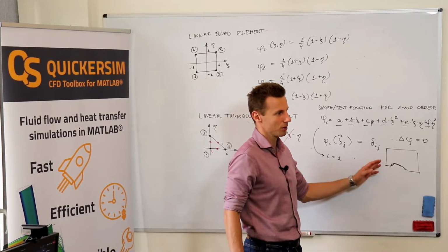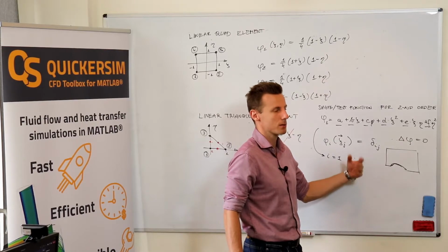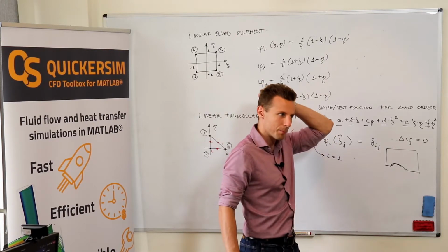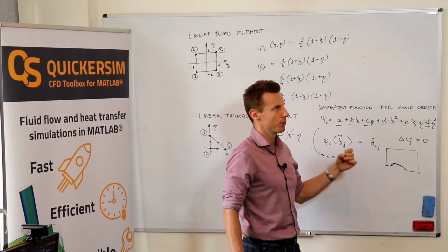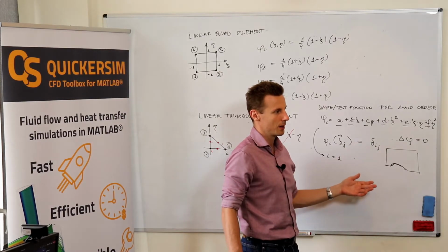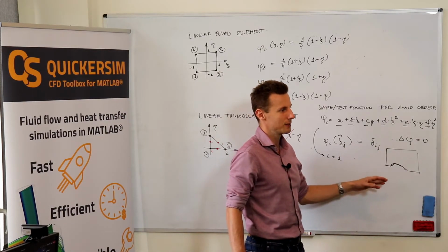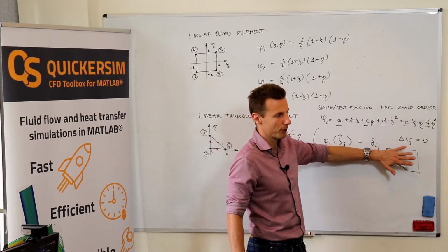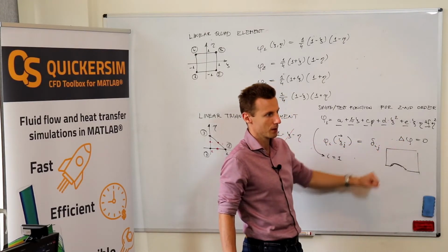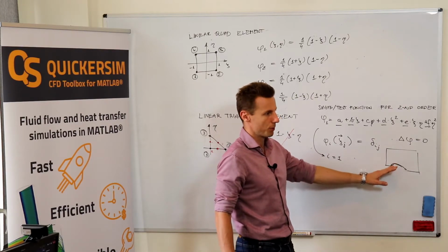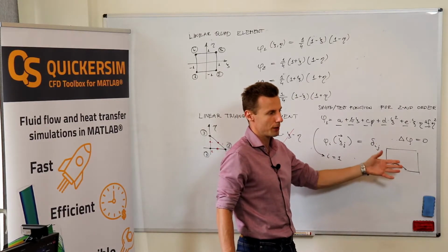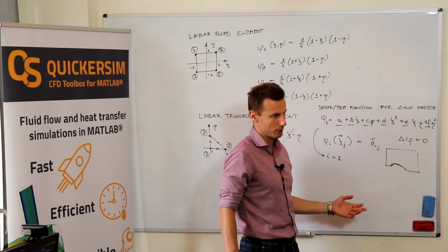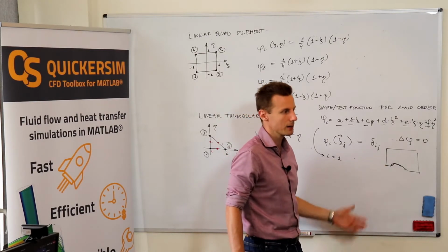You still gain some accuracy because you've got a high order scheme, but if you go to third, fourth order, etc., your accuracy decreases if you keep the overall number of unknowns in the system constant. So that's one of the problems. Obviously, you can extend to nonlinear representation of the geometry, and then it's fine.